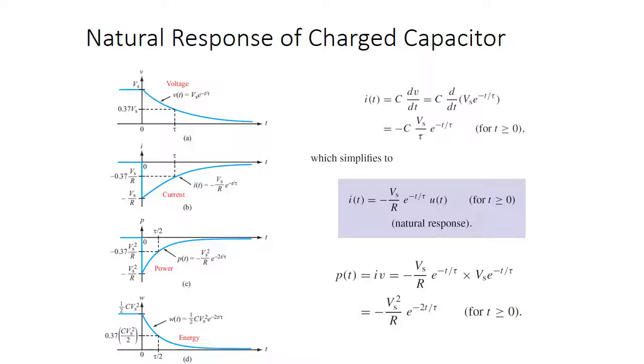And the rate that it decreases is going to be your natural response. That's the equation we just looked at in the previous slide to look at how that response behaves. As you go out to infinite t, you're going to get closer and closer to 0 because that capacitor is going to be drained closer to nothing. And this is going to be on a decreasing exponential slope because remember, we had that e^(-t/RC). So that's going to give us our decreasing exponential as well.